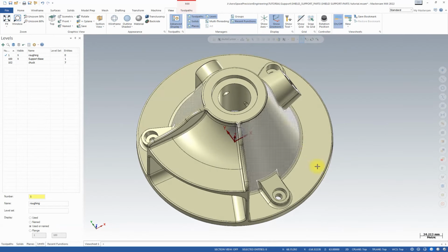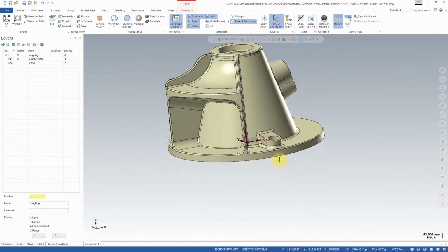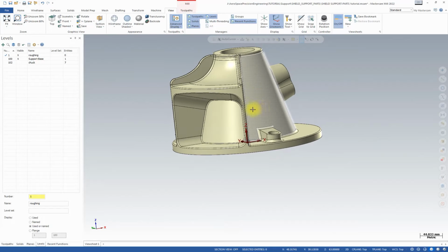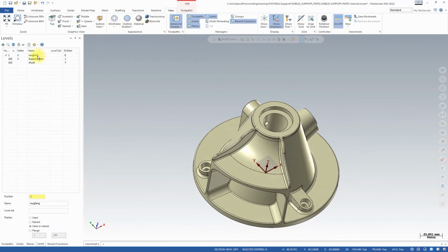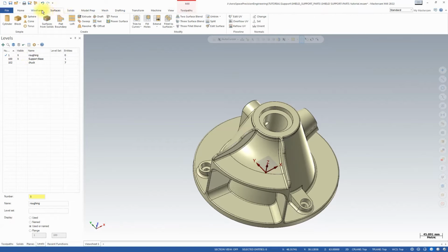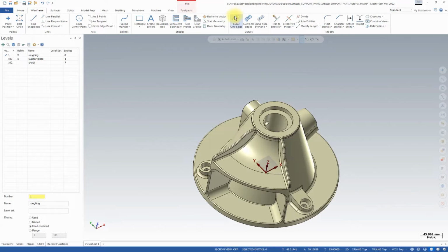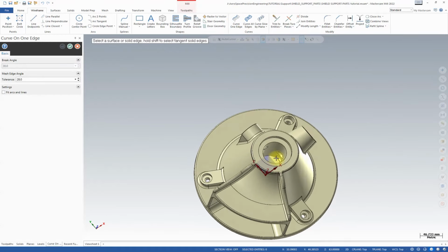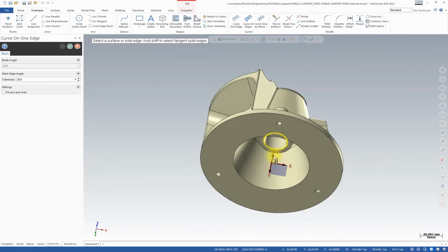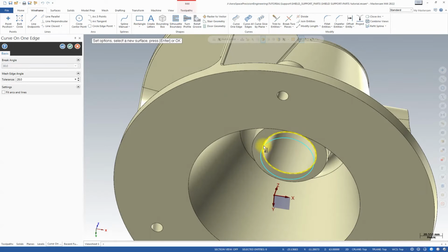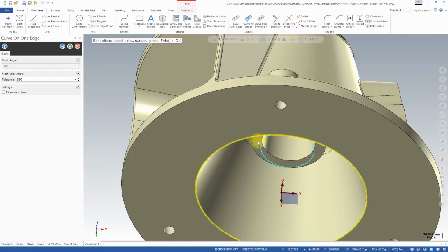And because we are using 2D, everything we select will go to 63 mil Z depth. Okay, so somewhere here. Okay, and with that level active here, I'm going to surfaces, wireframe, curve one edge. I'm going to create a curve on this edge here. So as you see, because we are on the 2D mode, I created that wireframe geometry from curve one edge on that height here.